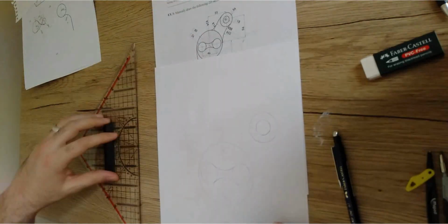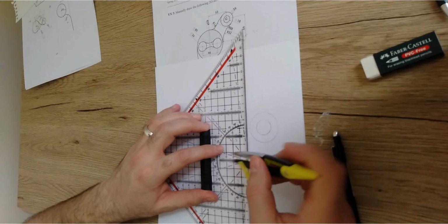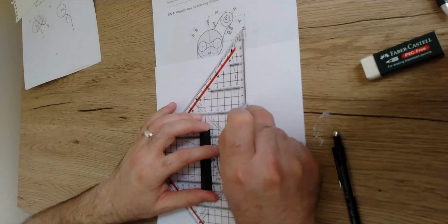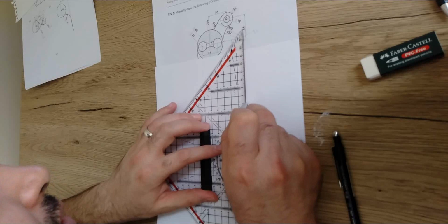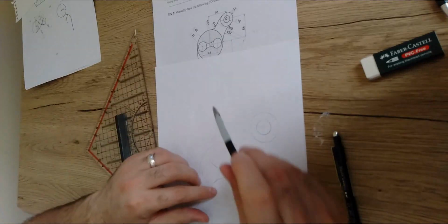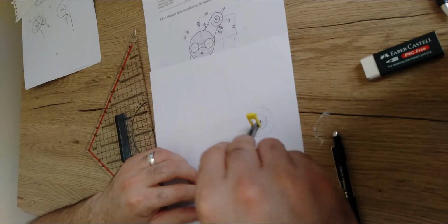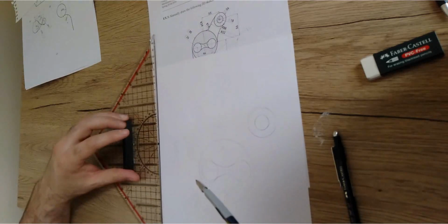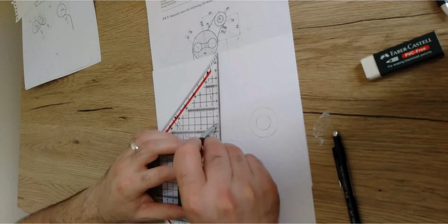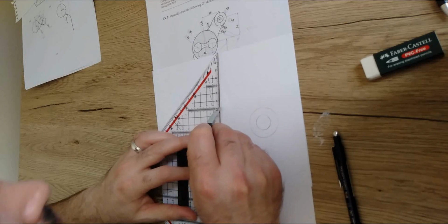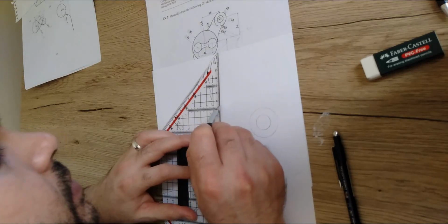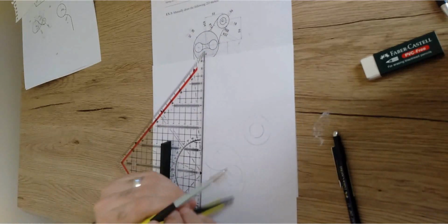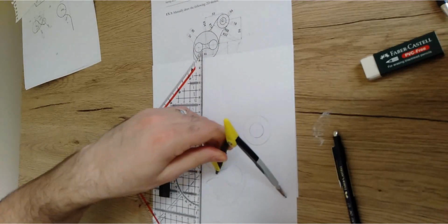So first I'm just gonna open the compass twice, one time with 70. Make sure that it is perfect. Then from the center of the small circle, draw a curve with the 70. It's gonna be the first locus. Then you're gonna open with the 92 and fix at this point, then draw another locus.